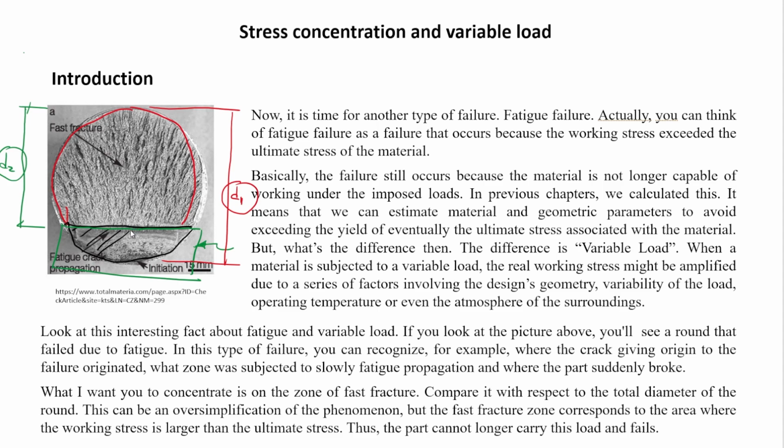But the fatigue failure means that the part in this case is going to fail because the remaining structure, after this part here was affected by a big crack in this section, could still do the job until diameter 2, where it was not able to hold the forces anymore and it broke. So there's a difference between the design diameter and the diameter at which it breaks. And this big difference depends on which safety factor you used for your design, which type of considerations, which type of failure design theory, and other unknowns that we're not taking into account.